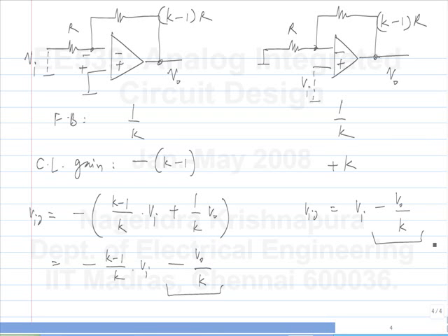Okay. So, in both cases, before we had evaluated that the relative error in the transfer function will be 1 over the loop gain and so on. So, in both cases, the relative error will be the same, although the closed loop gains are different. Okay.